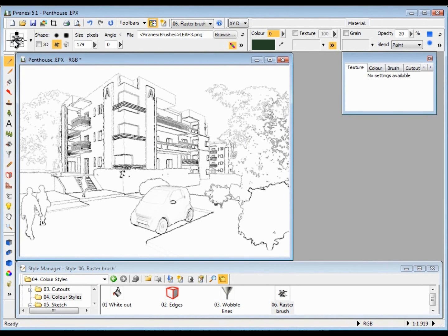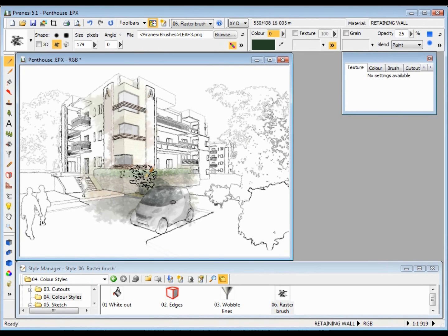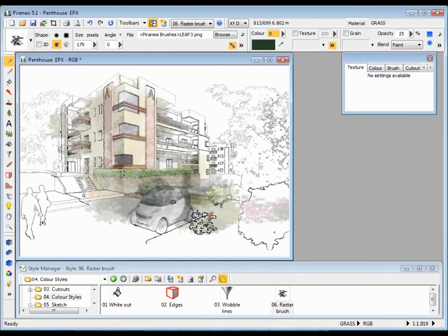a raster brush. We've got a round brush that we've used before, but you can have raster brushes as well, just a little raster file. And then I'm going to paint with a very, very low opacity there. I'm going to turn it up just a little bit, the colour back into the image. And there you have it. One sort of photorealistic and then washed out painted effect to finish.